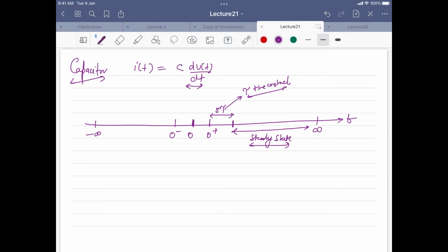Because all the charge of the circuit is basically in it. So what? Current is allowed to go into it. No, but if it is storing the charge, then what's the problem? Voltage change is not allowed? No, that's not the reason. It is that the amount of charge leaving is equal to the amount of charge that is coming. So what can you say about the current in that case? If the amount of charge leaving is the same as the amount of charge arriving into the node, what can you say about the current flowing in that capacitor? Is it a constant current? Steady state current, right?